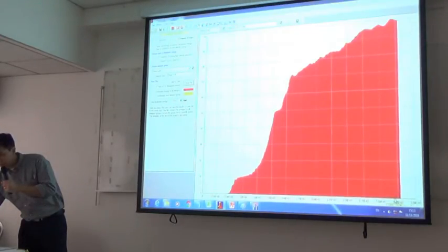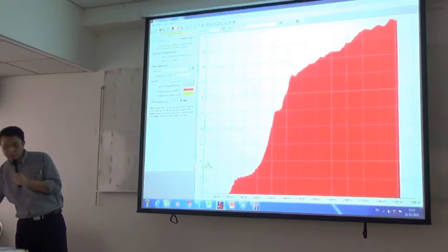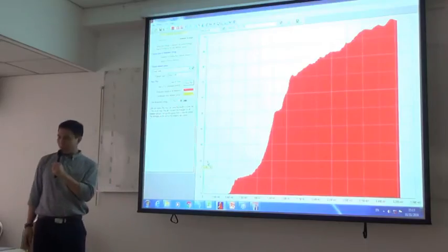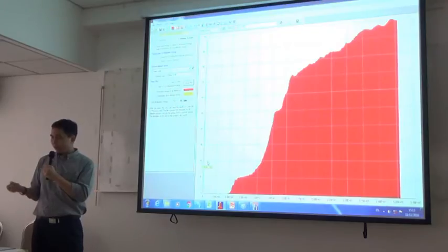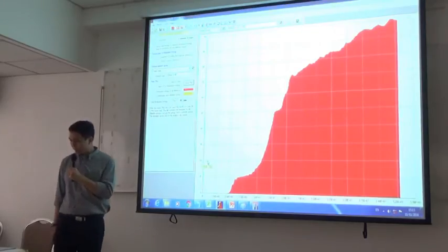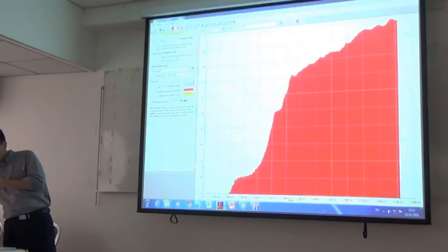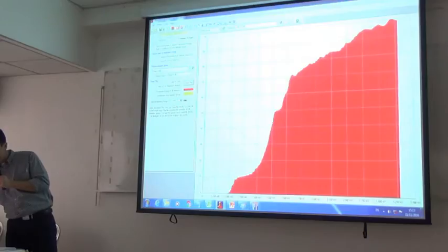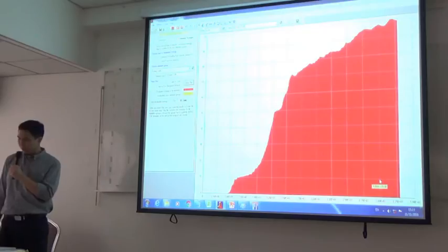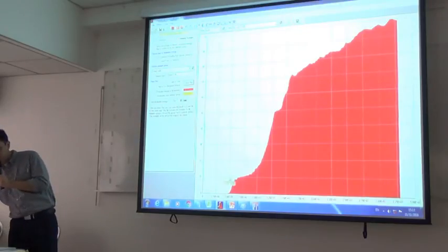Here we can see that the shear wall is not yielding at all. The y-axis is the percentage of the energy dissipation from that selected group. The yellow one is the energy dissipation from that selected group, but the yellow line is very small at the bottom. The red one is the total energy dissipation. The x-axis is the duration, the earthquake duration in seconds.